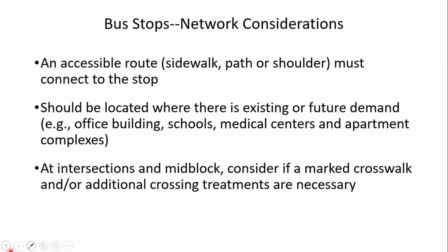In terms of network considerations, there needs to be an accessible route, sidewalk, a path, or a shoulder to connect to the bus stop. And this should be located where there's existing or future demand, for example, office buildings or schools or medical centers, residential complexes, destinations of that sort that generate demand. And at intersections and mid-block, consider if a marked crosswalk and or additional crossing treatments might be necessary.